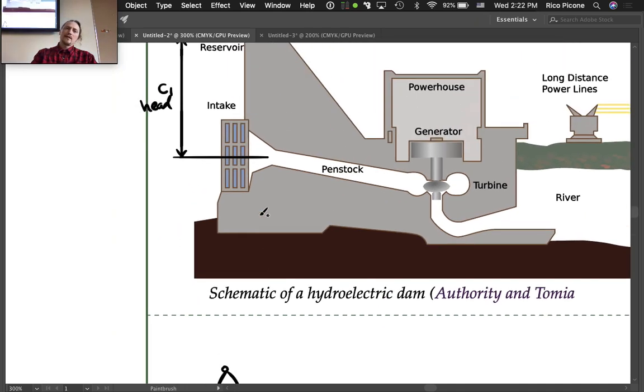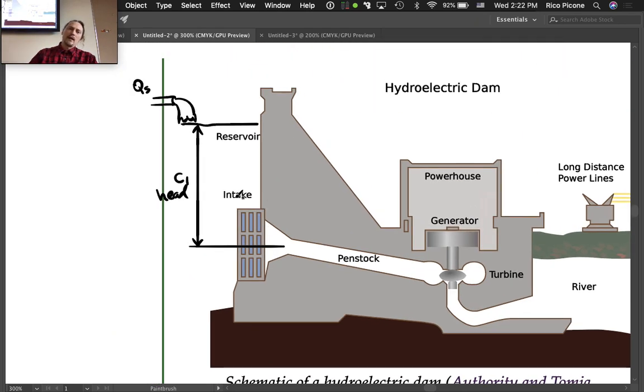And at that point, we get down to this intake. And so the intake is going to want to be filtering out debris and whatnot. So most likely it's going to be a sort of grate and potentially some screen if they need to, depending on, you don't want debris to come into your turbine. So it's at least got to filter out a pretty decent amount of stuff.